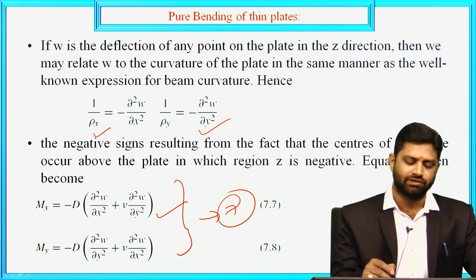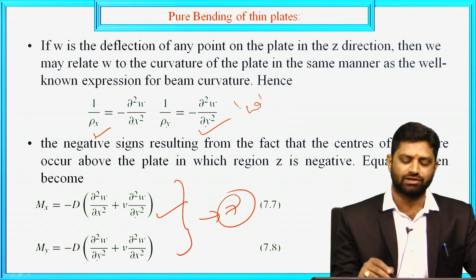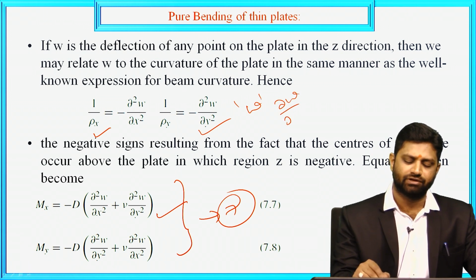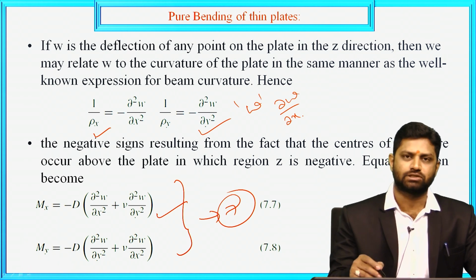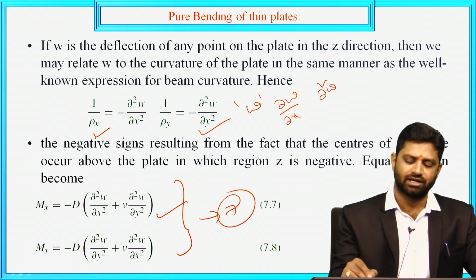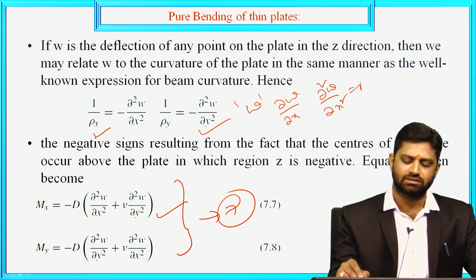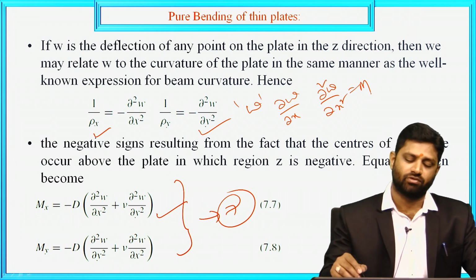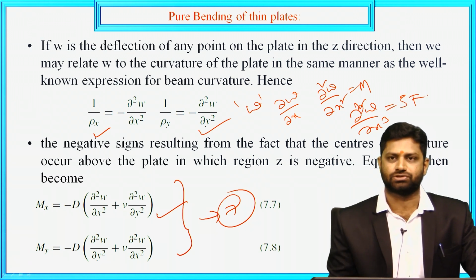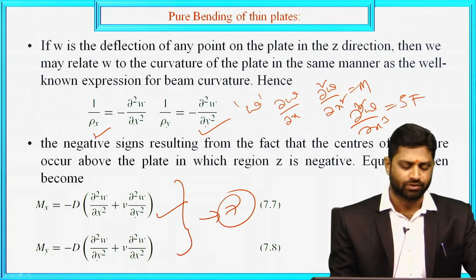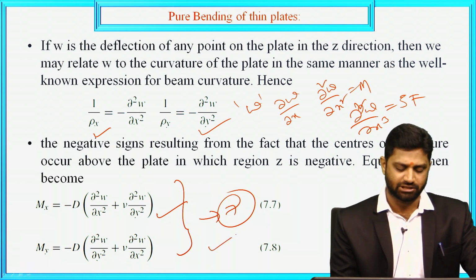As we know, we are considering W as a deflection, and the differentiation of that deflection with respect to any parameter we call slope, and when you differentiate one more time, we call this moment. And if you differentiate one more time, that is the third time, then what we are going to get is shear force. So this we need to know. Equation 7 is responsible for this.